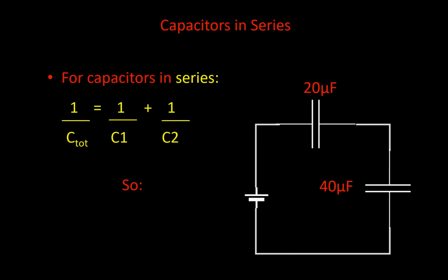So in this case, if we're to add our two capacitances, our 20 and 40 microfarad, we have to say 1 over C is 1 over 20 plus 1 over 40. So invert each, add them together, and then invert the answer. If you invert these two and add them together, you will likely get a number that's like 0.4 or 0.6. Not entirely unreasonable, but yet the wrong answer. You would then have to invert that value to get what you needed. And in this case, we're looking at a 13 microfarad capacitor.